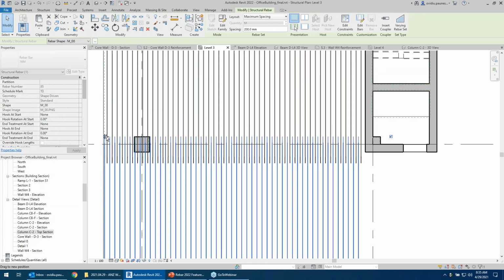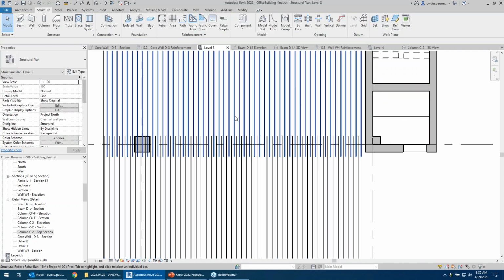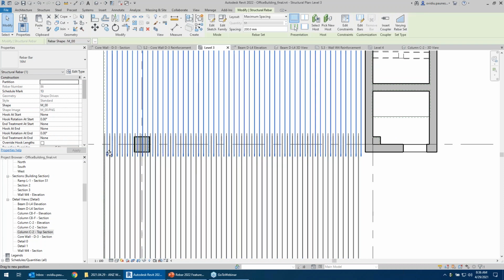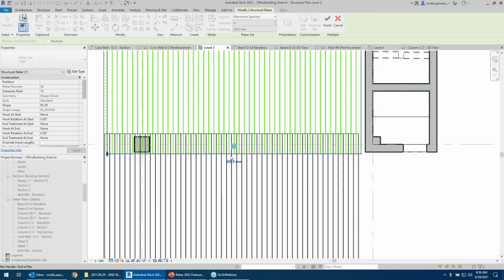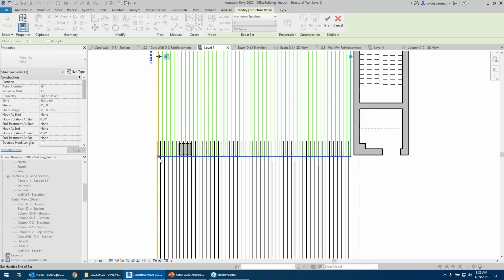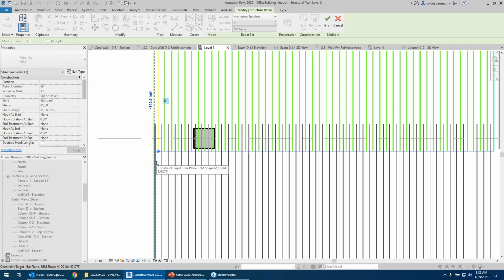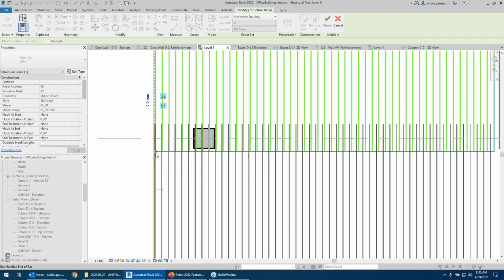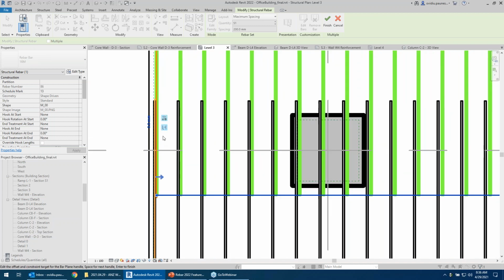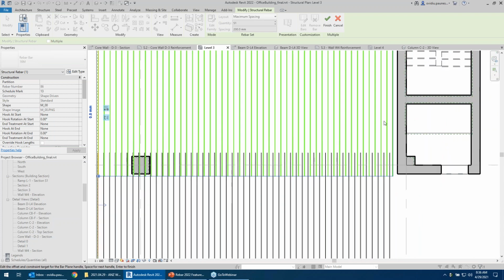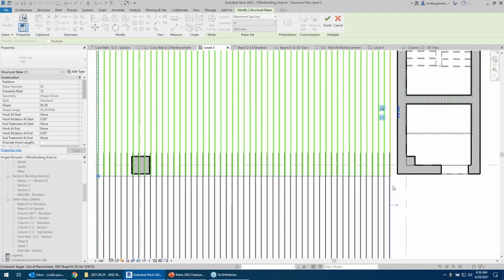we will notice that when adjusting one of the sets, the other one follows. This is because when connecting the ends, the two-way constraint is automatically enabled. This is the two-way constraint, which we can do for the other segments. So if I want these sets to have the same start or be connected at the start without clashing, I can enable this two-way constraint, and for the other side as well.